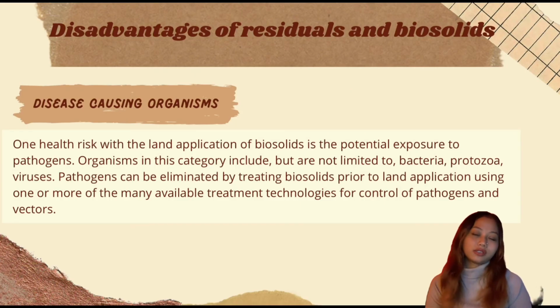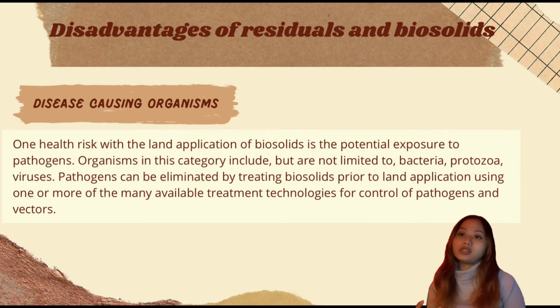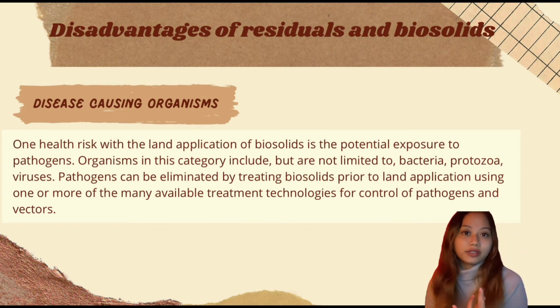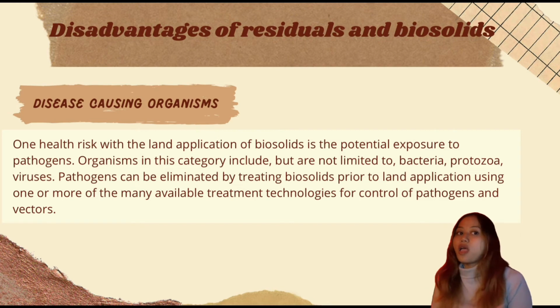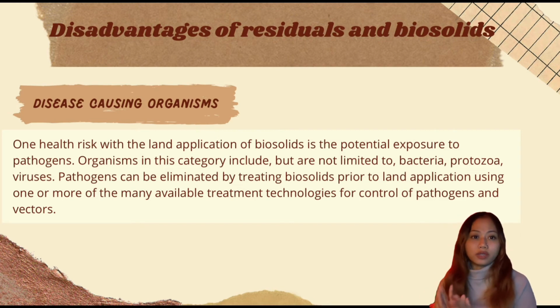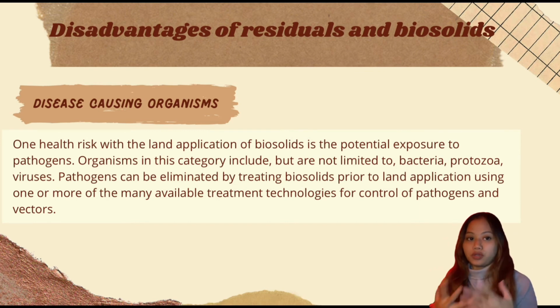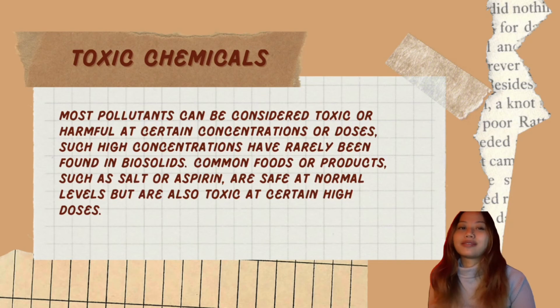So the disadvantages of biosolids are, the first one is disease-causing organisms. One health risk with the land application of biosolids is the potential exposure to pathogens. Organisms in this category include, but are not limited to, bacteria, protozoa, and viruses. Pathogens can be eliminated by treating biosolids prior to land application using one or more of the many available treatment technologies for control of pathogens and vectors.